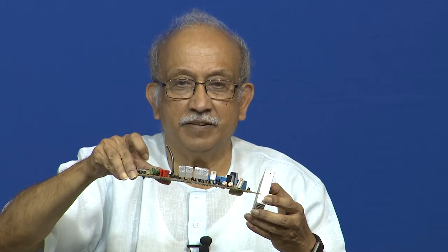To enable conduction, why can't we make this wider? But then we will end up with the problem of not having enough space for the air to pass. This is where the complications of the modeling become important. You understood, no? So, take some typical heat sink that you have, and imagine something were to be mounted here, directly attached to the power device. Typically it could be a heat bridge. In this case we had direct access to these power devices.